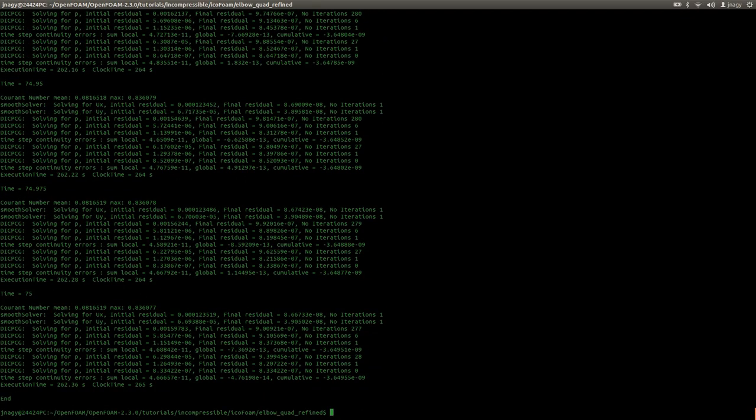Okay, now the simulation stopped. It ran until 75 seconds. It took a little bit longer. And now you see that the maximum Courant number is 0.83, so there is a definite change.